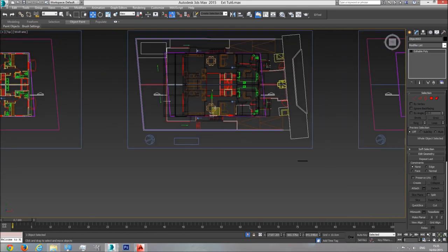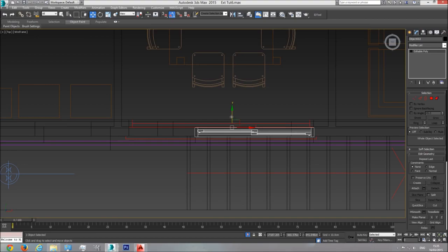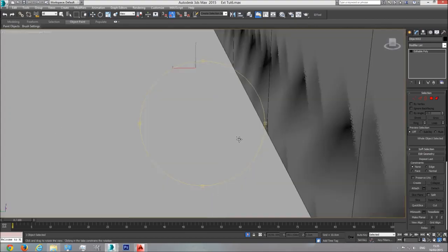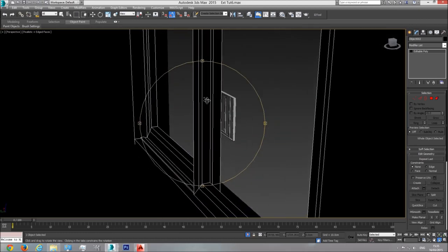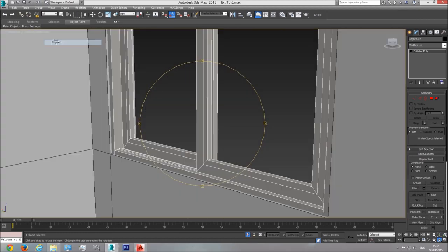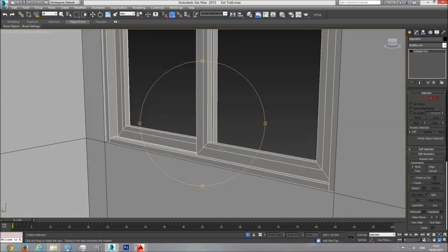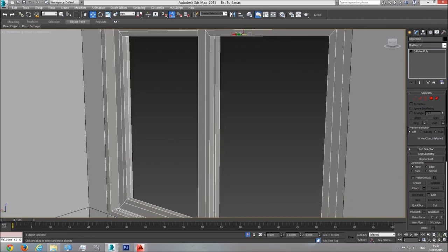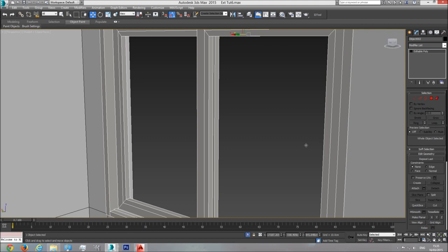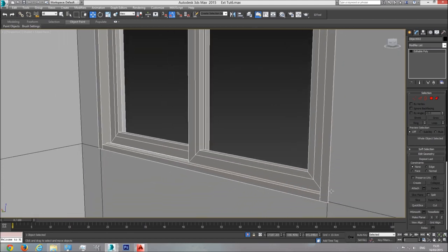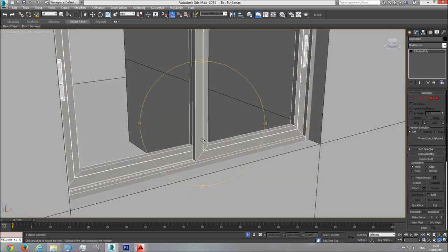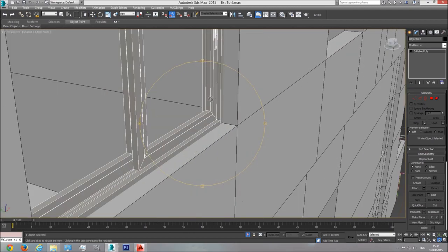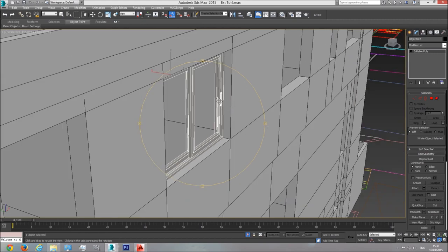Now, let's place it in the window itself. If we look in the interior here, let's do shaded. Okay, so now I put a camera inside of the building. That's because I want to place the window correctly. So I'm going to take it on the y-axis only, take it back a little bit so it covers the wall just a little bit inwards. And as you can see, you have a little piece of space between the window and the exterior wall, which is fine.